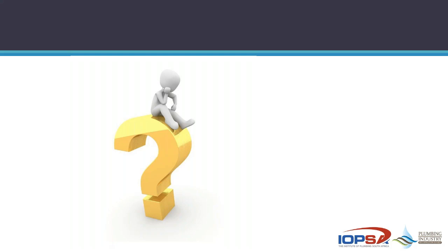There's a sewage flow from buildings, and you've got to allow for that, the rate of sludge and scum accumulation, and then the most important one that they deal with, there we go, in situ test pit and test hole. So if I could refer the sender of that question to page 50 in 10400 Part P, that says that you need to dig a hole 300 by 300 by between 300 and 350 deep, and you end up filling it with water.